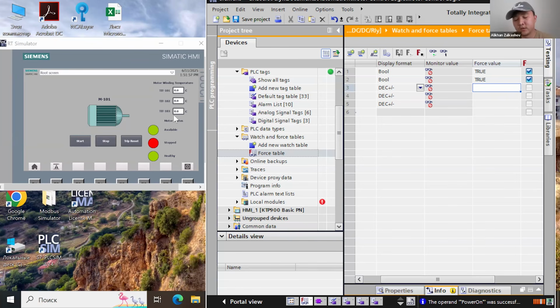In industry, for example, at least in the oil and gas industry where I work, we have two separate controllers, one for process monitoring and control, and one for the safety system. Whatever sensors or final control elements are responsible for safety will be connected to the safety controller.